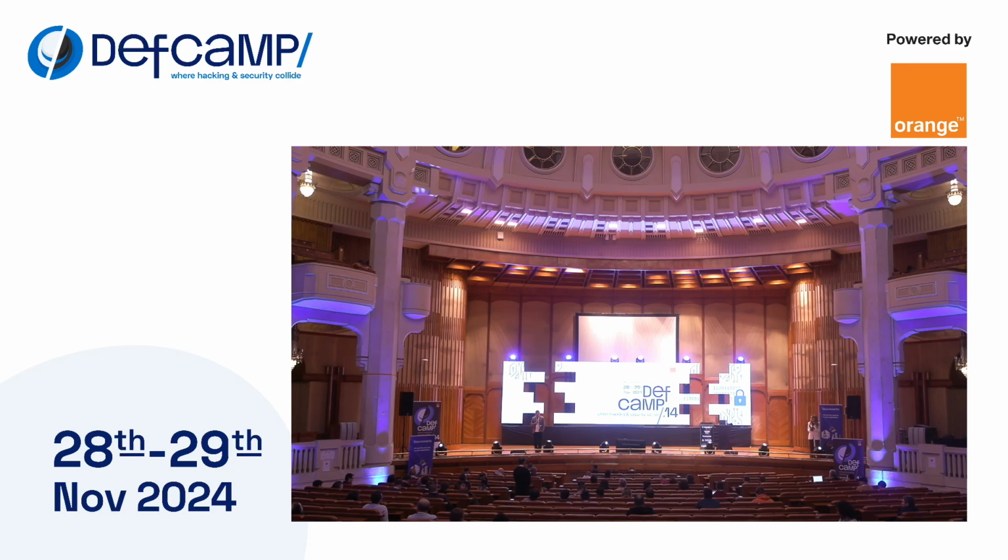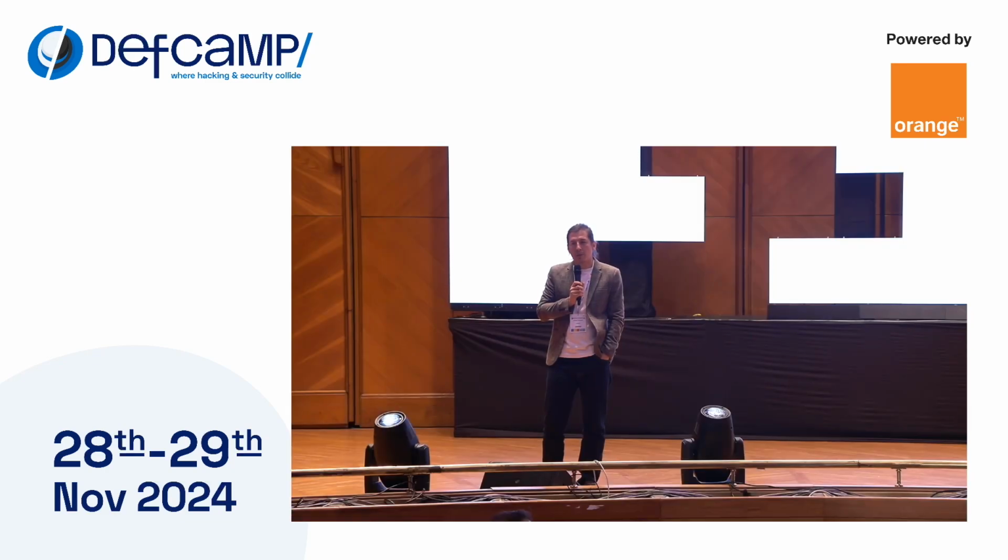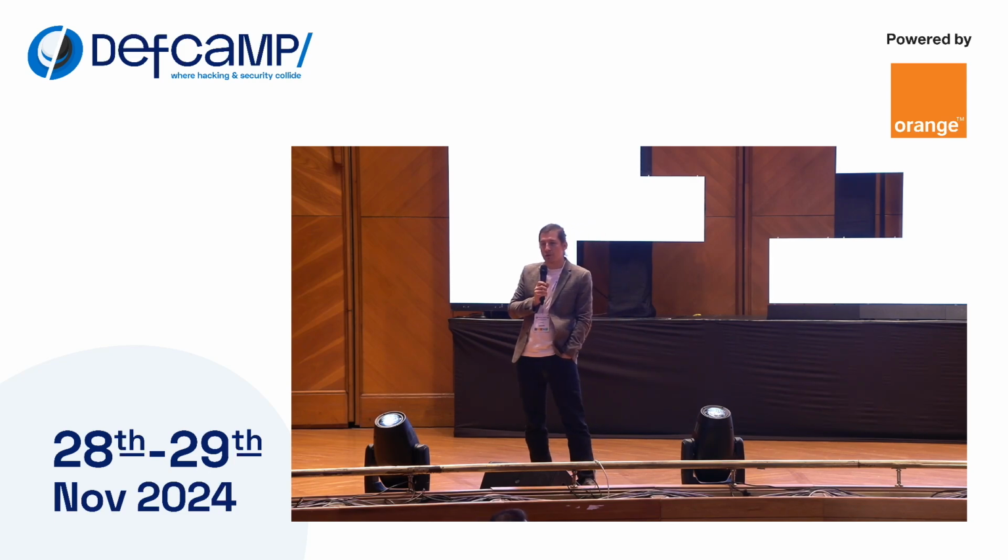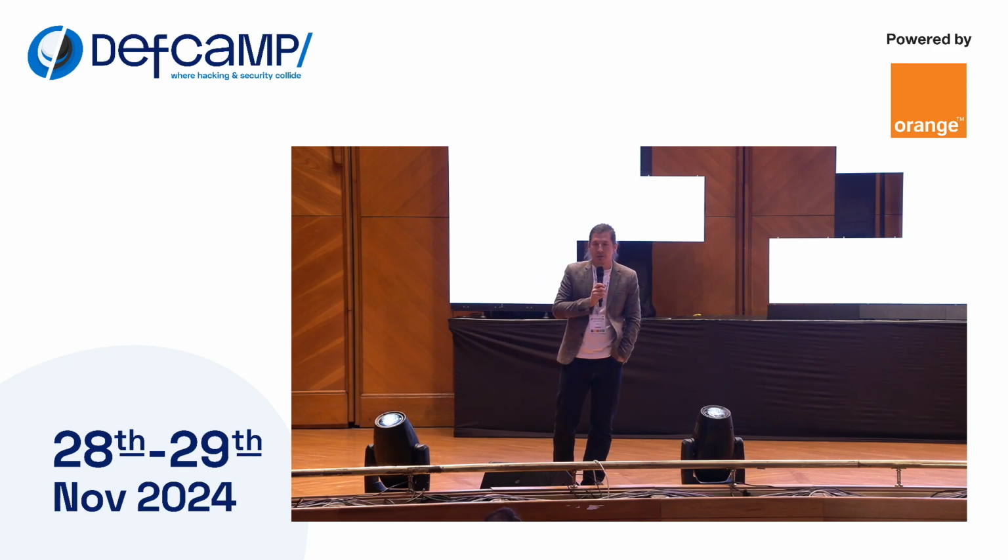Yes. Good question. So that's mainly a job for an industrial firewall that sits before the PLCs. With a bit of machine learning and the ability to look into the traffic, so with deep packet inspection, and the ability to understand the traffic and the parameters that are allowed, we can block actively, or we can just notify. OT people are not a fan of blocking, obviously, because that might give them headaches if they block something. But they for sure want to be notified if something is off, so they can act.